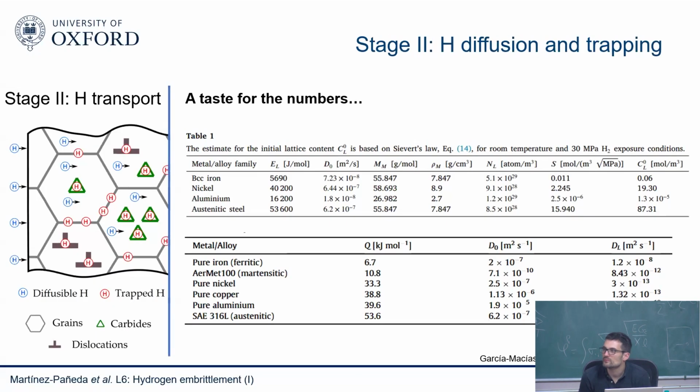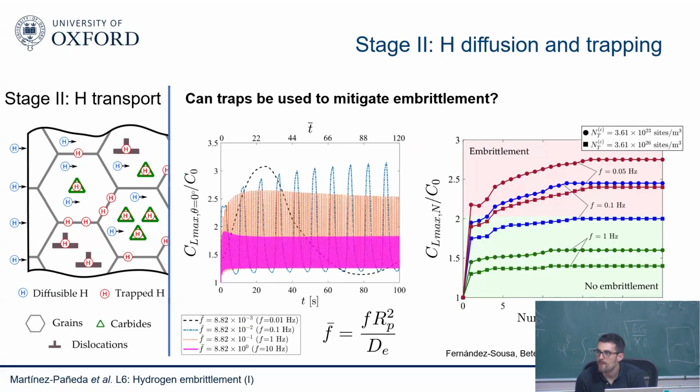Yes. In the previous slide, you mentioned traps, which is carbides. Can you please comment about what is the nature of the interface? Covalent, semi-covalent, incoherent? Yeah, this is another question, and a lot of people ask. It's a good question, a highly debated topic. A lot of people would actually argue that maybe a carbide is what initiates the entire embrittlement. You see the grain boundary cracking because grain boundaries are the weakest path. So once you initiated a crack, then the crack will decide to go to the grain boundary. But the cohesion of the carbide is actually what drives the entire hydrogen embrittlement process.